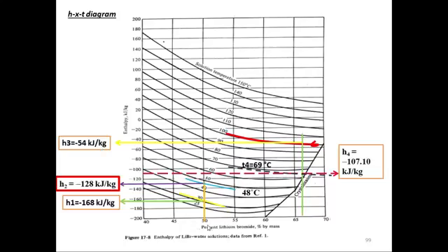And in the absorber the concentration was 50% and the solution temperature is 30 degrees. So the point is crossing here, and from here I can show this green line. This green line reads the enthalpy value as H1 equal to minus 168 kilojoule per kilogram.